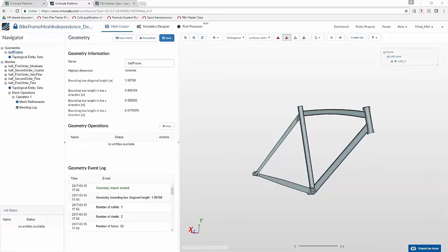And great, there's the last final question by Aditya. He wants to know if a second order mesh uses a quadratic function for interpolation, and if there is something higher, maybe a third order mesh. Yes, this is available in theory, but right now at SimScale we only have first and second order elements, which should be enough for 99% of all engineering problems we have.